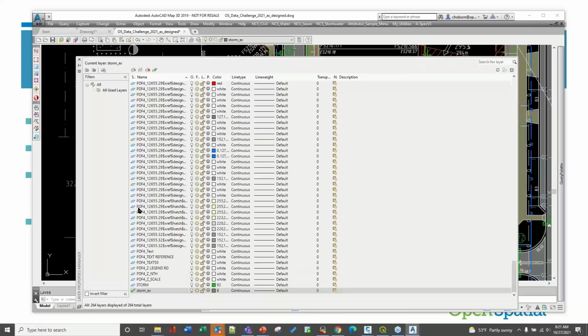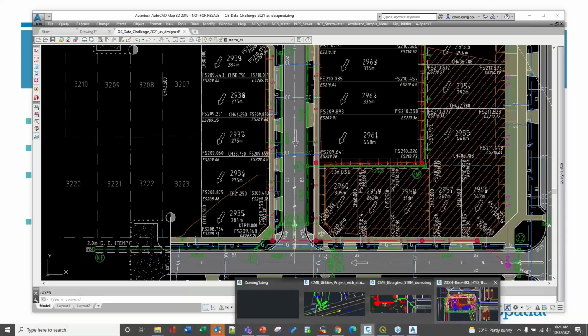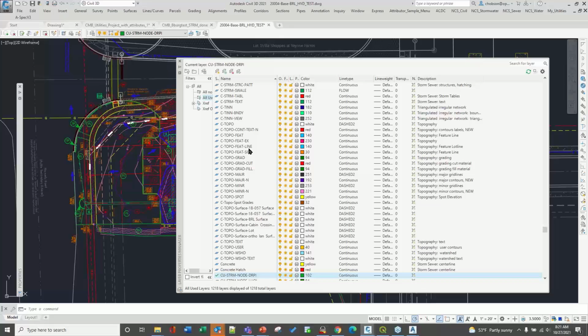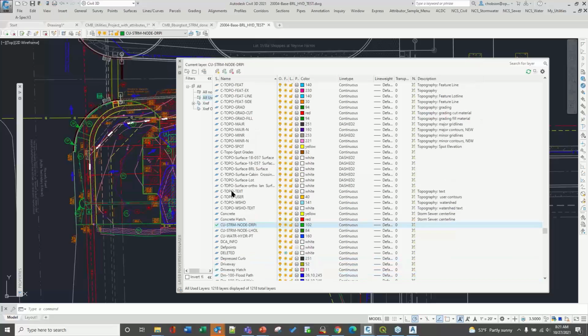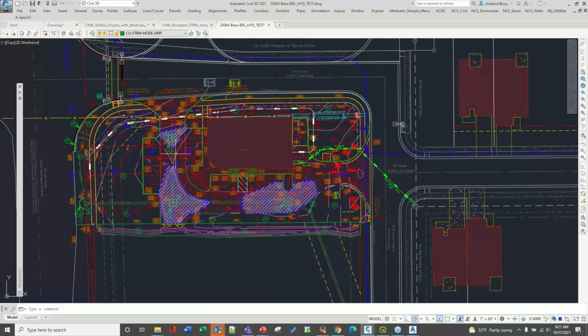If you look at the layers, there can be any kind of layer naming going on here. There can be, you know, the way in which these are structured. And if I look at a few others here, let's take, say, this one. So here, at least, we've got layers that are, you know, National CAD Standard compliant, but have they put the right entities on the right layers? And furthermore, how do we get to attributes?